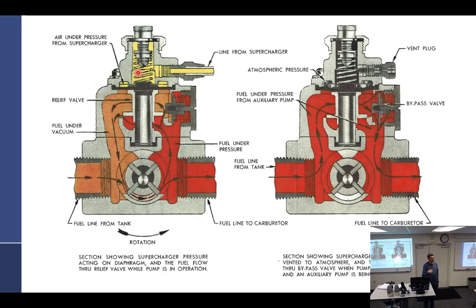Let's think about what's happening inside. It's left-hand threads. So as I screw it to the right, inside is left-hand threads. So what is that nut doing? It's coming out. If it comes out, which way is it pushing on the spring? In. Is it pushing down on the spring? No, pushing out.